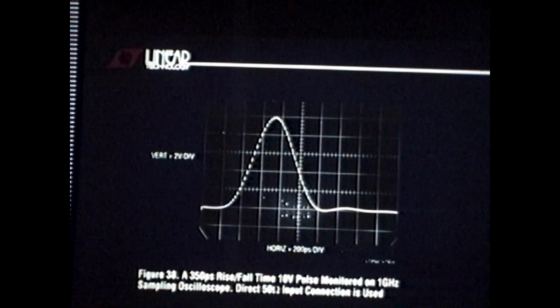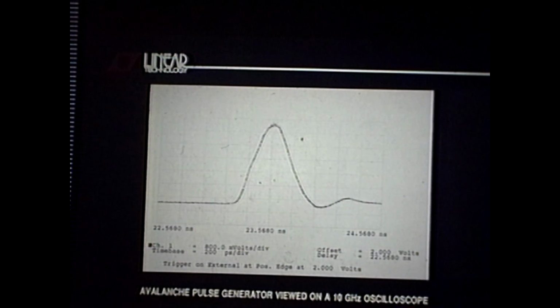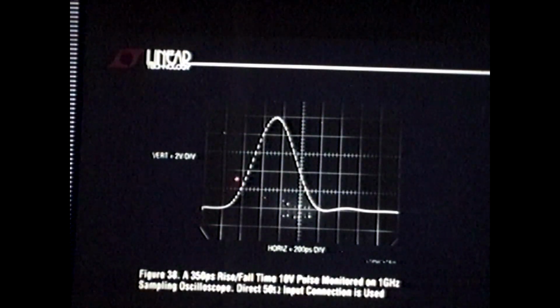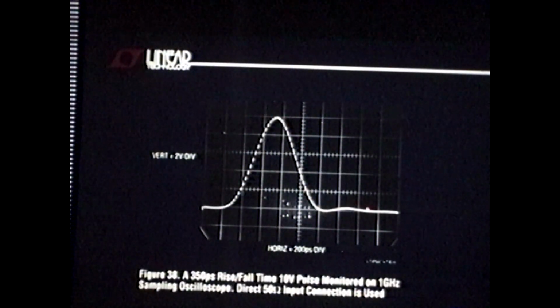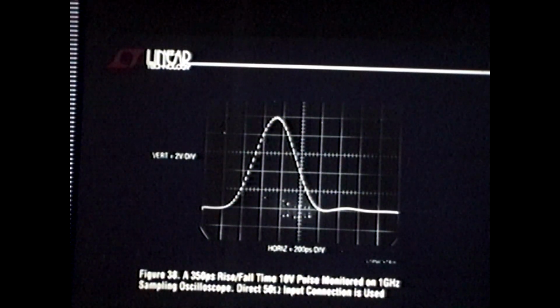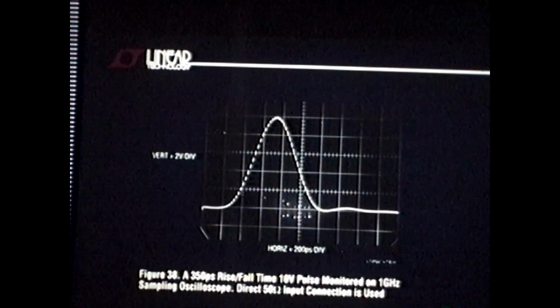To get the answer, we have to go to God's own oscilloscope. One Sunday afternoon, I went into HP on the Hill, a fire-breathing, nitrogen-cooled monster oscilloscope. In a 10 gigahertz bandpass, when you see edges that look symmetrical at speed, something may be bandwidth limiting, and it is.